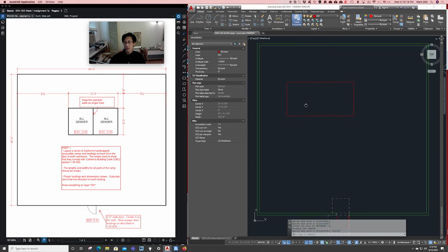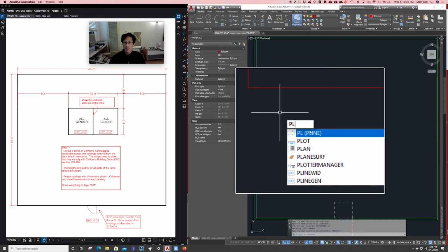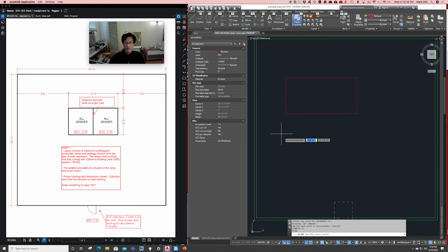All right, let's draw the box another way. Let's use a polyline. Similar thing, and I'll show you the difference between drawing with Polyline and drawing with a line. The Polyline shortcut is PL. P-line is the actual command you see there. So let's just start anywhere again. Click, move the mouse in the direction I want. I want it 16 feet. 16 feet, enter. Move down this way.